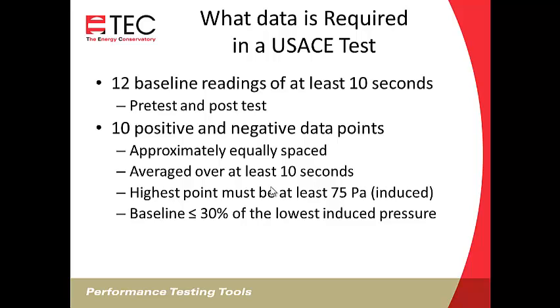On that test we did, 10-story building with about 30 degrees outside, we had about a negative 20 baseline. And if you want an induced pressure during a depressurization test, you'll need to go to negative 95 to get a change of 75. So the software will cue you after the baseline how much you need to adjust your target number forward to get an induced pressure of 75. It'll tell you how much you'll need to adjust it by. So it prompts you to make that change after the baseline period of record.